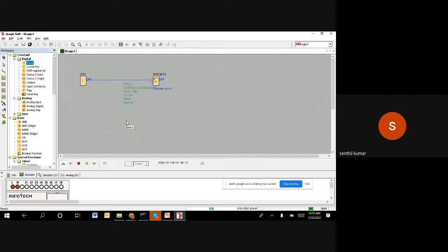I'm in simulation mode. This is our bottle sensor. Once the bottle comes near the sensor, it is going to go on. Now you can see the count, the blue value here, has changed to 1, because it counted 1. But remember, it is always on. If it stays on, it is not counting.